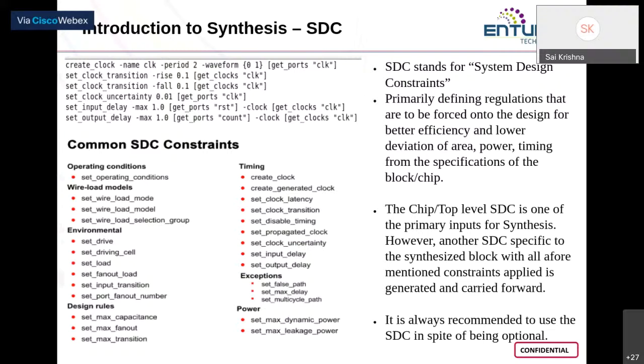Yes, for different technology nodes, you'll have different .lib files with different values for each design and its pins. And yes, the constraints applied during synthesis will help the process. As I said earlier, your synthesis happens in 3 stages: translation, mapping, and optimization. Whenever mapping is being done, let's take the same example. If an instruction y equals negation x is being mapped to your liberty file, your liberty file may contain several inverters, each one having the same functionality but different driving strength.